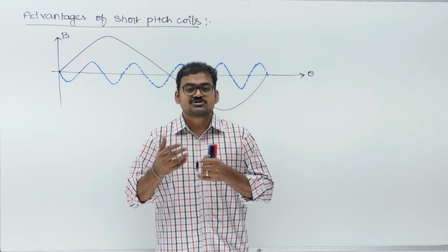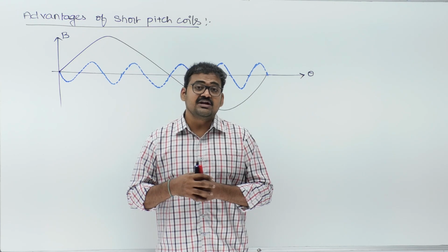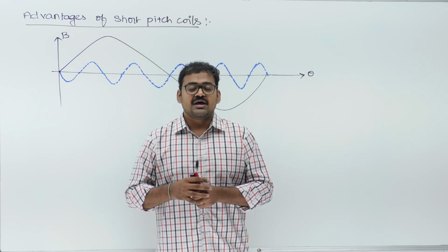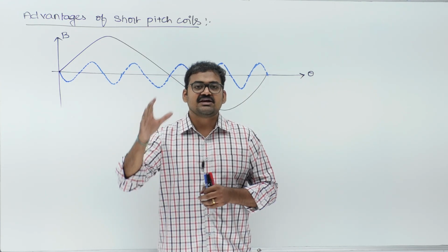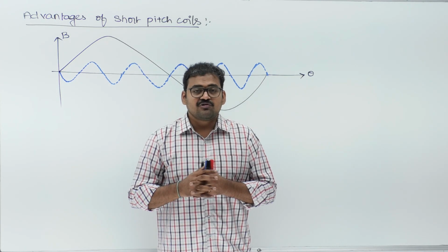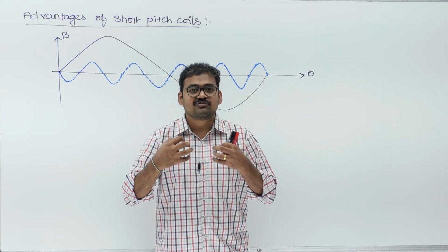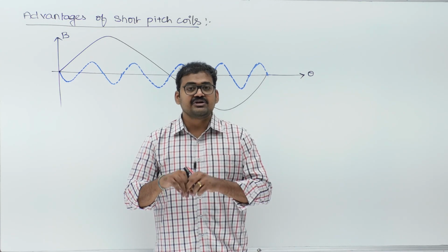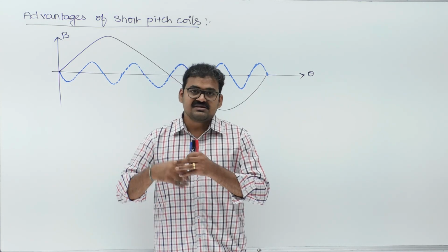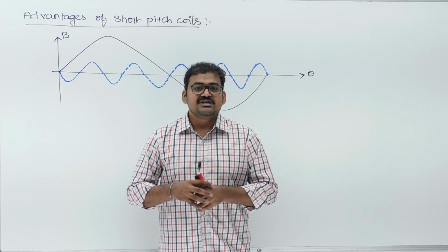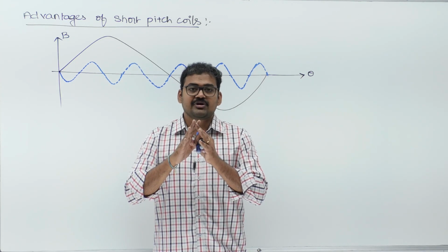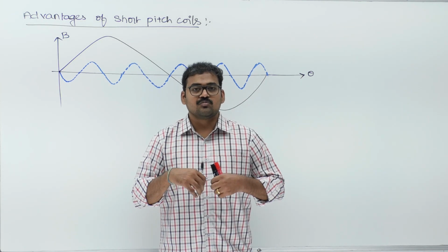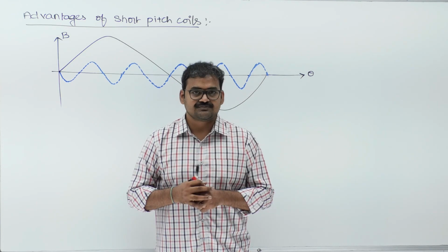In most alternators, especially cylindrical rotor synchronous generators, the magnetic flux wave is a flat topped waveform. Therefore, it consists of a number of odd harmonics. Even though it is non-sinusoidal, it is symmetrical in nature. Therefore, even harmonic flux components cancel, and only odd harmonic flux components exist.